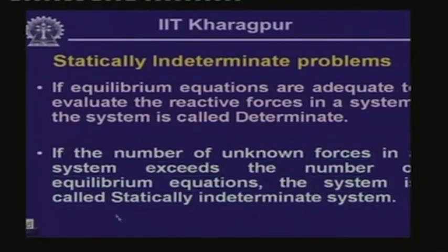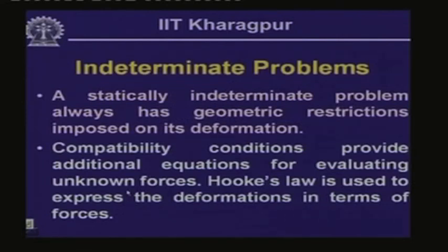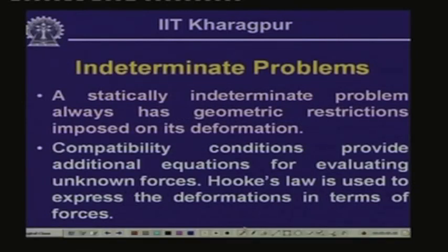For the solution of these indeterminate systems, we will have to find ways by which we can generate additional equations from which we can solve these unknown reactive forces. A statically indeterminate problem always has geometric restrictions imposed on its deformation.